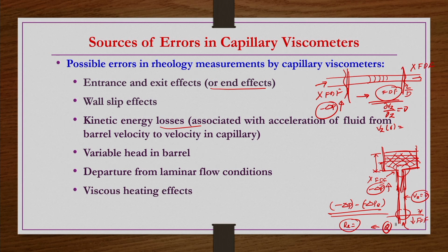And then viscous heating. As we discussed, most of the non-Newtonian fluids are multi-phase components. It is not a single component kind of thing. It is not true for all the cases, but the majority of non-Newtonian fluids are a kind of multi-phase flows, where some particles, bubbles or drops are suspended, like particulate systems, emulsions, suspensions, etc. So, when you have these kinds of multi-component systems passing through a very narrow gap, we maintain a narrow gap so that the changes in the shear rate or shear stress should be negligible. That is the reason we are taking the narrow gap.